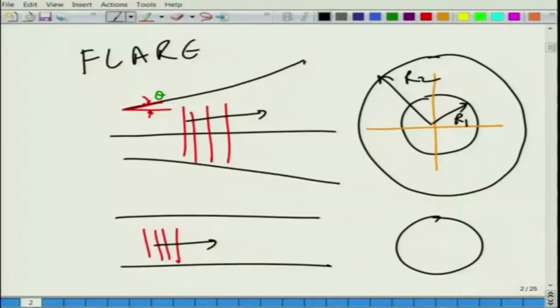This may not be true for all frequencies, because in some frequencies almost the entire acoustic power is transmitted downstream. But we will be basically focusing on the frequency range in which at least some part of the acoustic power is transmitted back upstream and less amount of power is transmitted downstream.